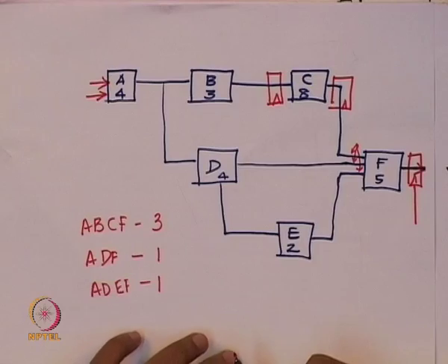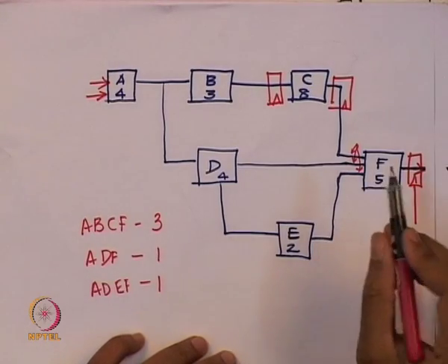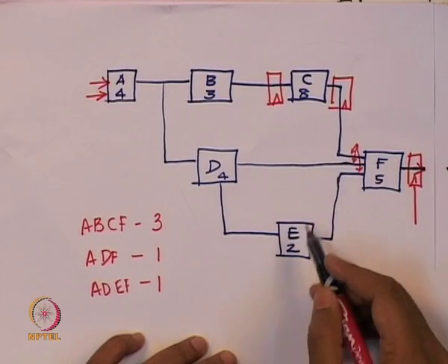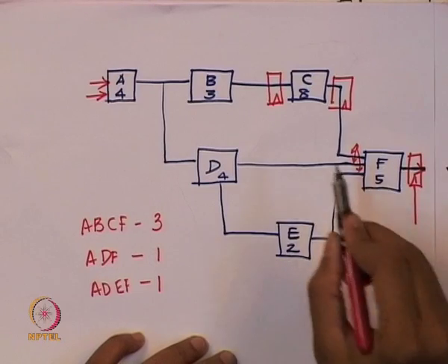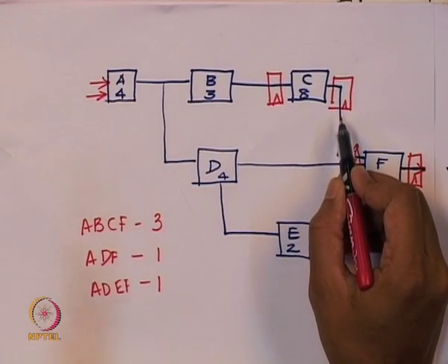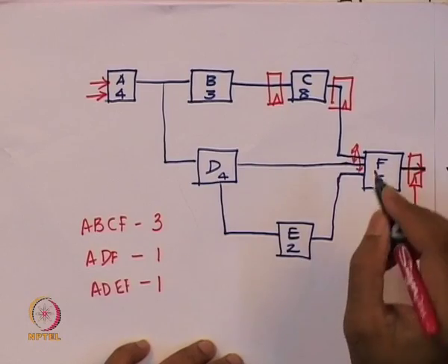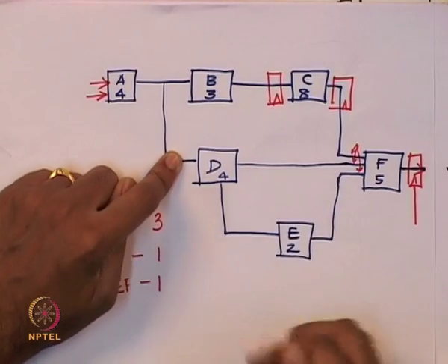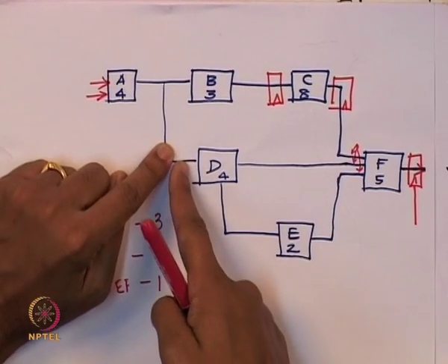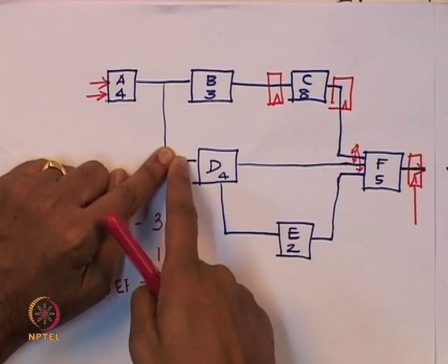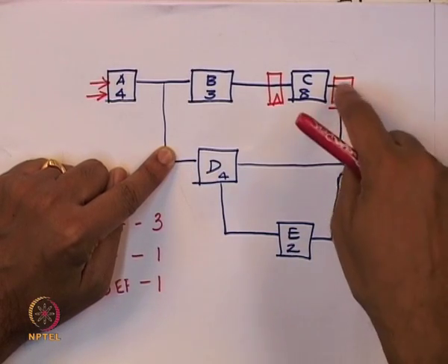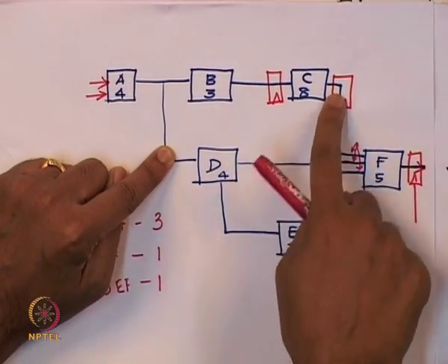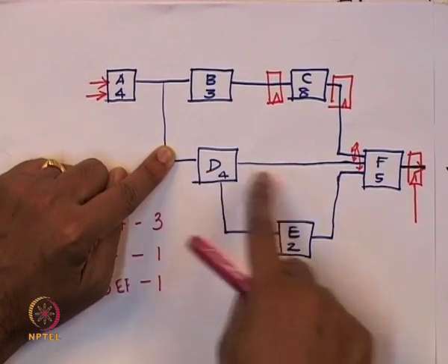To make this 3-stage pipeline, let us look at this picture again. So I have already placed a flip flop here. So F is supposed to process inputs that are all coming from the same input stage. So a simple thing to do is, let us say I put a flip flop here, for instance. I have already decided a flip flop for this location, it is at the output of C. Given that, now I have choices for where to put the other ones.